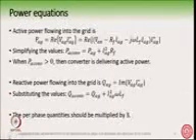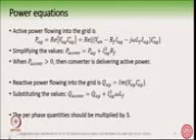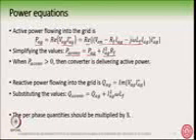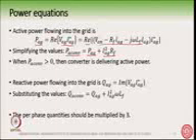Okay. So we can write the active power flowing into the grid as something like this. PAG is VAG into IAG star, and if you substitute the value of VAG as something like this, and simplify, you will see that the power produced by the converter is the power which is fed to the grid plus IAG square RF, the loss component in the filter resistance. So we have assumed this convention that the PA converter, if it is greater than 0, then the converter is delivering the active power. This is our convention which we will follow.